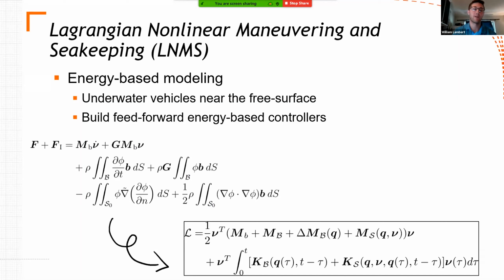So the final form is this top equation, and earlier on the parameters, these d phi dt terms, these derivatives, were populated using boundary element methods, if you look at those double integrals over the body surface and over the calm free surface. But we would like to further study these nonlinear effects using nonlinear codes.